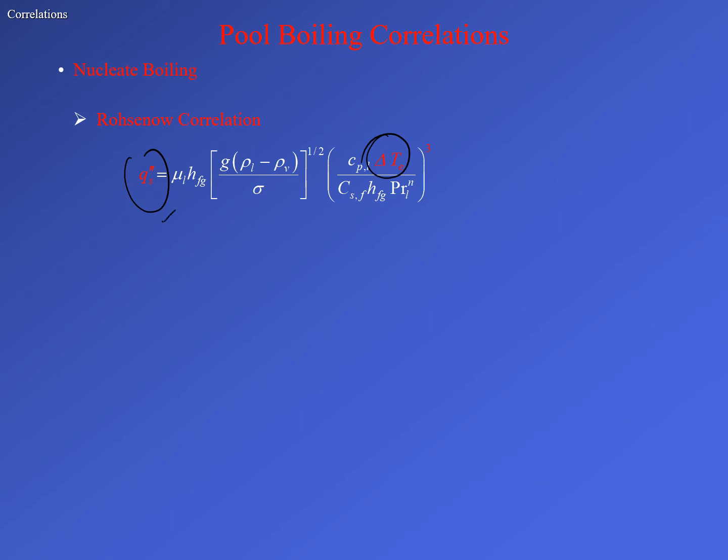You need all these parameters, as we discussed in the beginning: the Prandtl number, Jacob number, Bond number, as well as the modified Grashof number. We can put these variable values in and get our heat flux, which is typically what we want to calculate as a function of our excess temperature. And you can calculate your heat transfer coefficient from here as well.